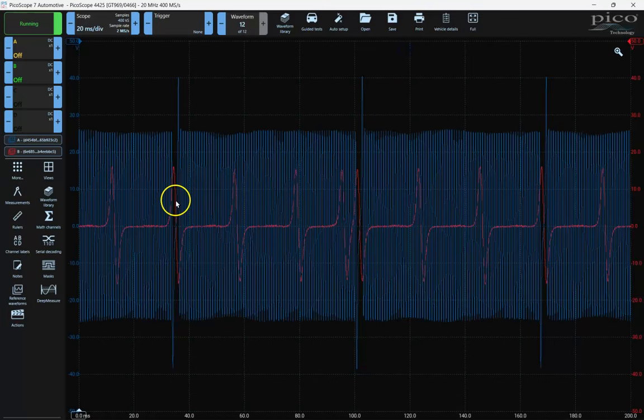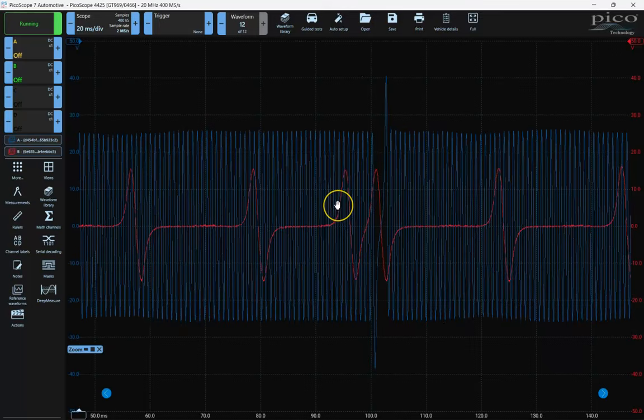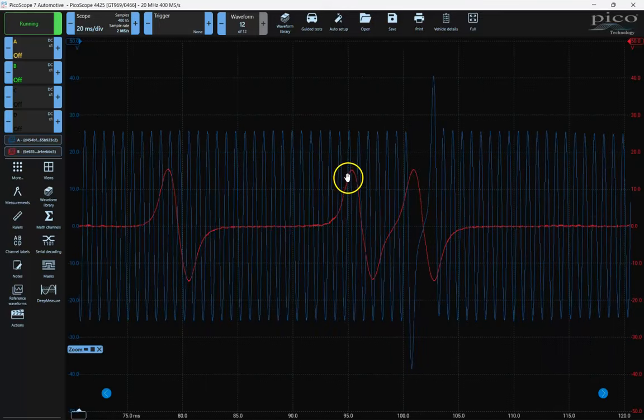So go ahead and get rid of these guys. If we look at the red signal, this is really cool. This is the cam position sensor. So that the engine controller, ECM, or as John Deere calls it, ECU, knows when it sees the gap in the crank position, it doesn't know if it's on top dead center of number 1 or of its companion cylinder. So to determine that, there's an additional pulse on a John Deere engine on the cam position sensor that it's going to read before it comes around near that top dead center number 1.